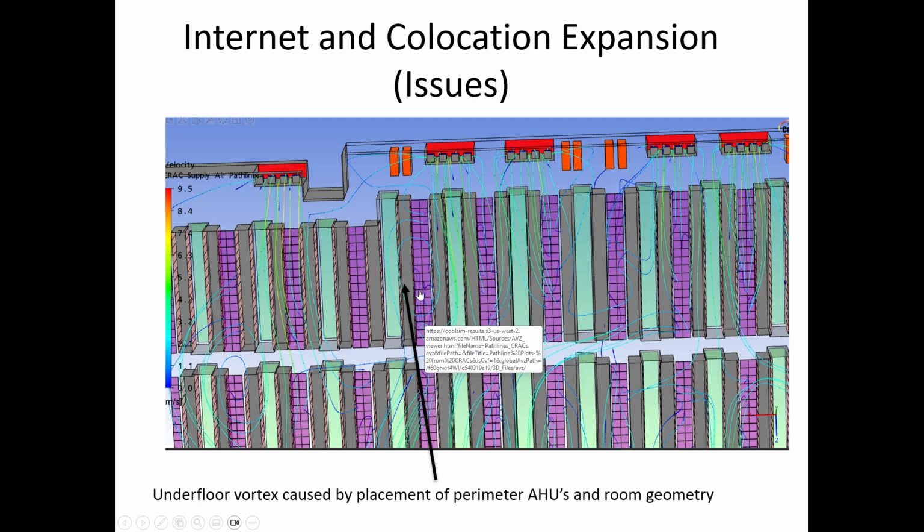That can be seen in this image. This is an underfloor image. It's a little hard to see here, but I'm looking at the bottom of that same cooling unit. It's blowing this way. This one's creating a block over here. It's blocking the air from coming this way. The little bump out is not helping, and that creates a small vortex right underneath, and that creates a low pressure.